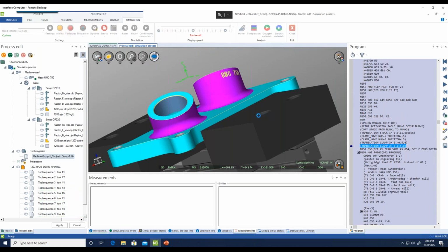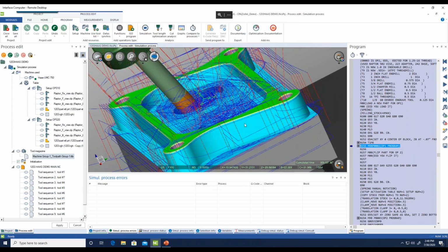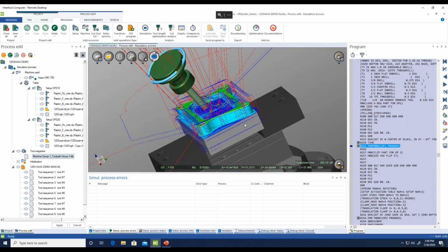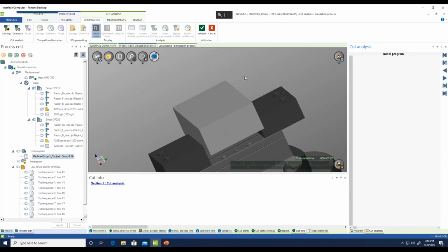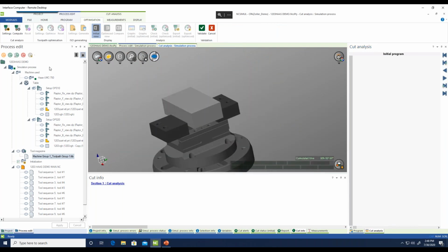However, beyond that, we're going to go into one of those optimizations like I was saying. So prerequisite, just make sure that you have simulated once and you don't have any errors, so you're not trying to optimize with an error-ridden code. But then all you have to do is hit this optimization button up here, and it's going to start the module.